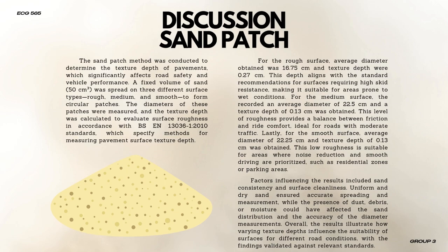Lastly, for the smooth surface, the average diameter obtained is 22.25 cm and the texture depth obtained was 0.31 cm. From this analysis, it indicates that this area is suitable where noise reduction and smooth driving are prioritized, such as residential zones or parking areas.